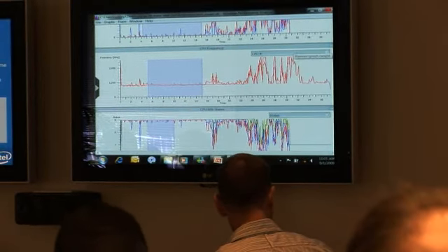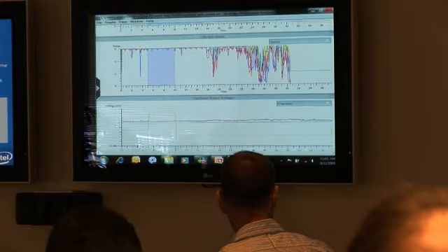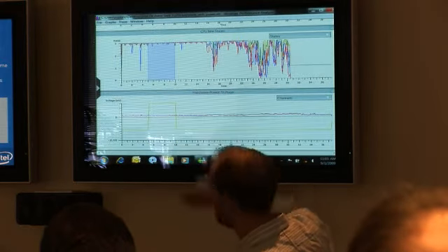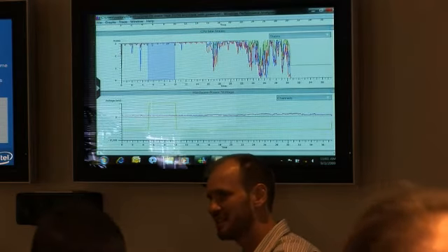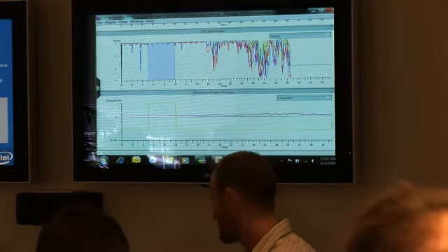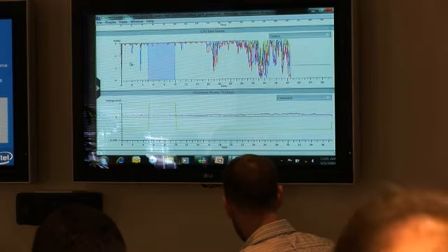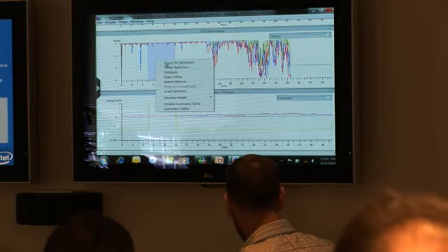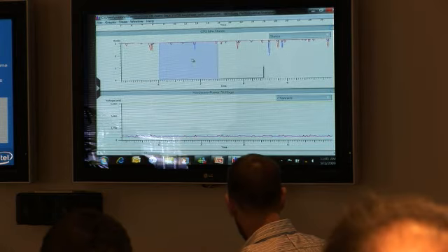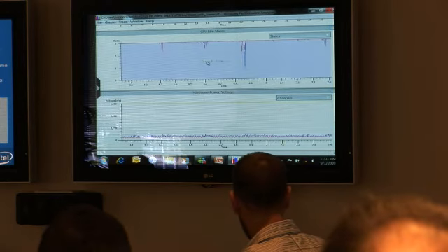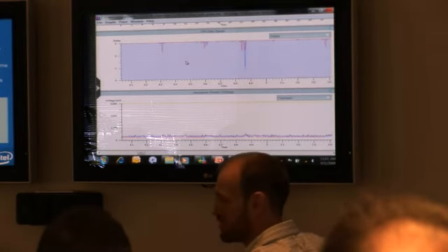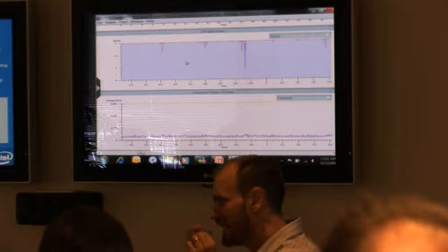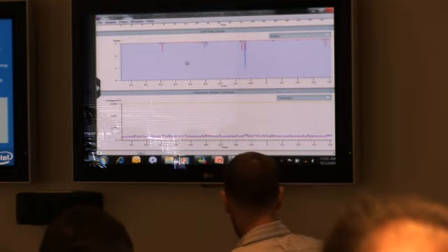If we jump down to the idle states, the graph at the top right now is the CPU idle state. Again, we want to get it down into these ACPI C states and the Intel C6 deep power down state. What we can do is drill into these sections to figure out what's actually happening in here. We can overlay data on what's creating timer ticks, and the result is we can find the culprits that are taking the system out of the deep power state.